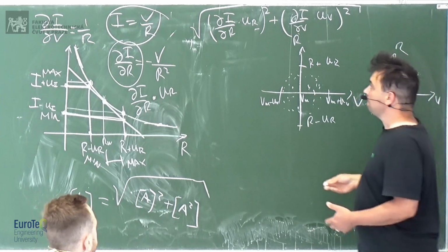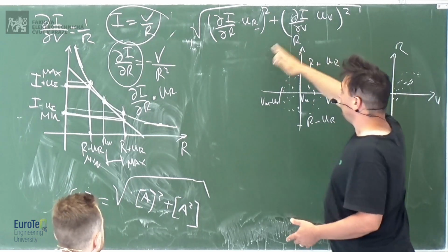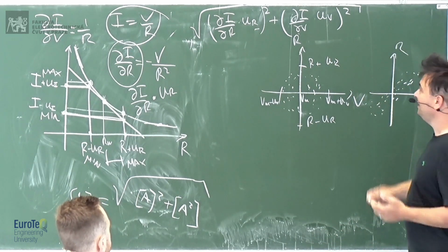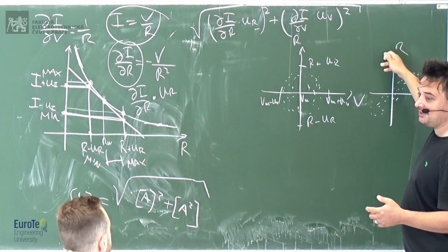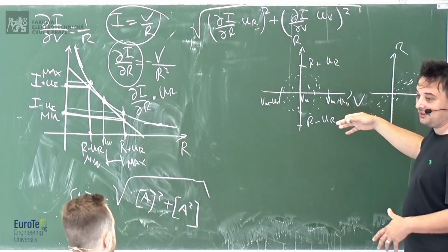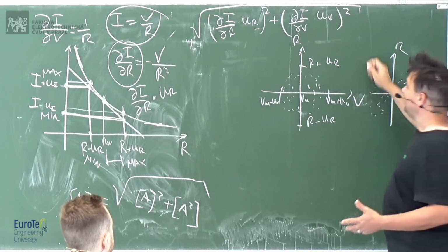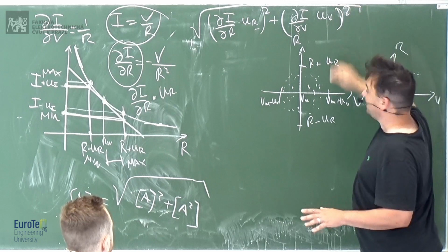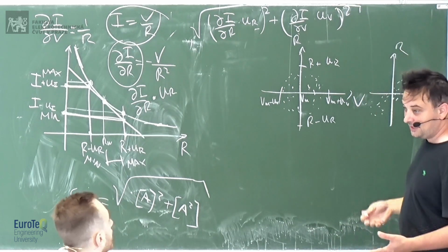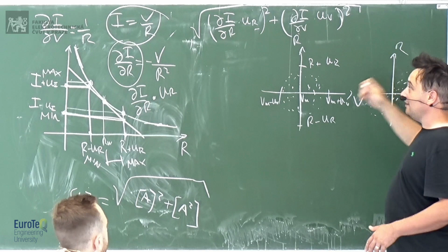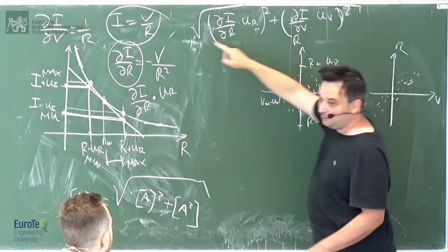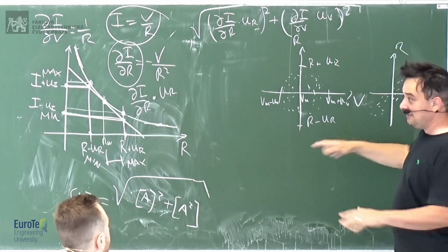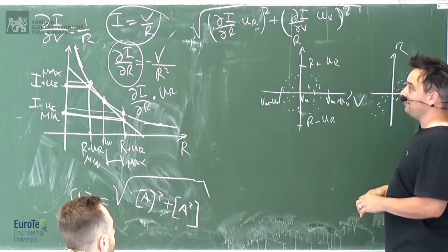And of course, not only two. There's a typical mistake: people think that if you have 3 or 4 sources of uncertainty, maybe some other component in the circuit which gives some uncertainty, they have to sum them with the cube. No. They are always summed quadratically. Yeah, because the square root won't work then. No, but then they take the cube root of the cube. No, it doesn't work like that. You always have to sum them quadratically, even if you have 1,000 different variables, okay?